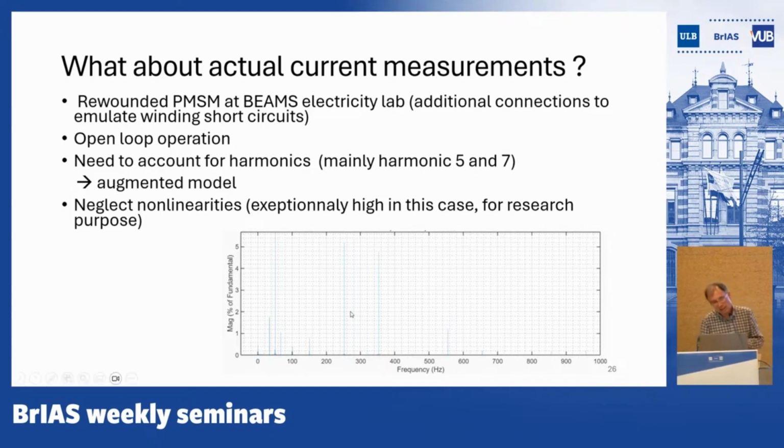These signals are made of several harmonics, and here is actually the Fourier transform of one such signal. And you can see that there is a fundamental here around 50 Hertz. And then you see harmonics 3, 5, 7, and 11 here, plus some other frequencies that are linked to nonlinear phenomena in the motor.